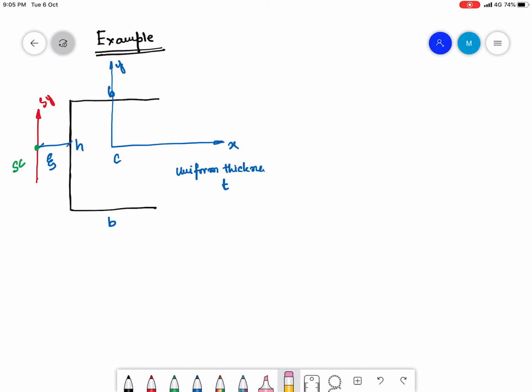Okay, now what is going to happen? Because of this applied shear force, there is going to be a shear stress distribution in the cross section. Okay, and this shear stress distribution can be represented by the shear flow Qs, where I know that Qs minus Q0 is going to be that huge equation, right?